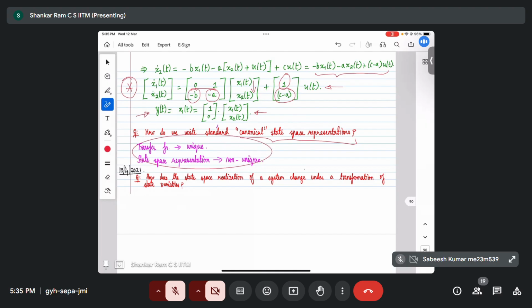Okay, so all those things we will learn as we go along, and that is where we use this important concept. Let us say we consider the mass spring damper system, which was m x double dot plus c x dot plus kx equals f, of course, I'm suppressing time. What was the transfer function? It is omega n square divided by s square plus 2 zeta omega n s plus omega n square. That is a standard form, correct, Roshan.